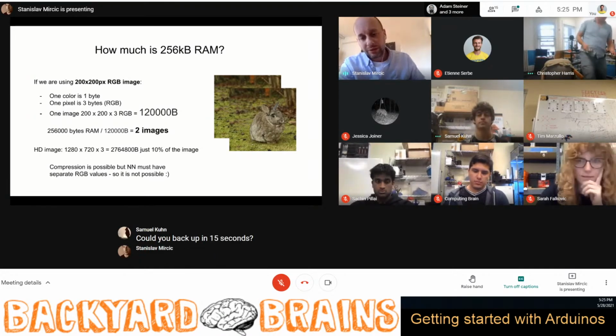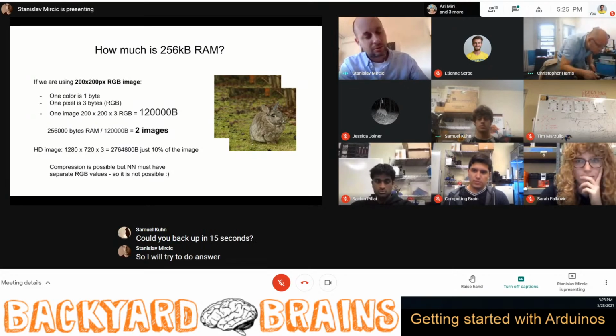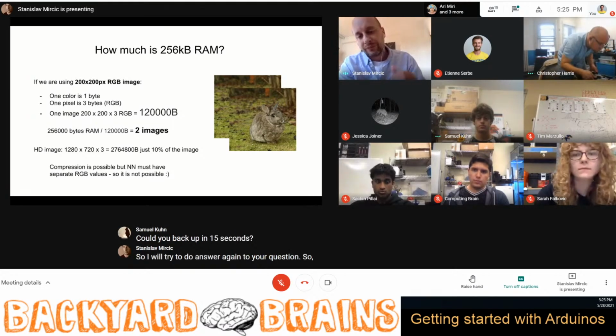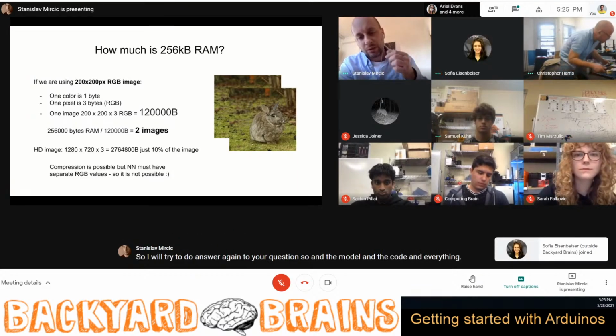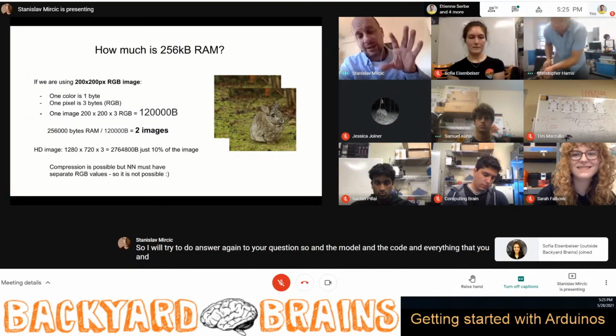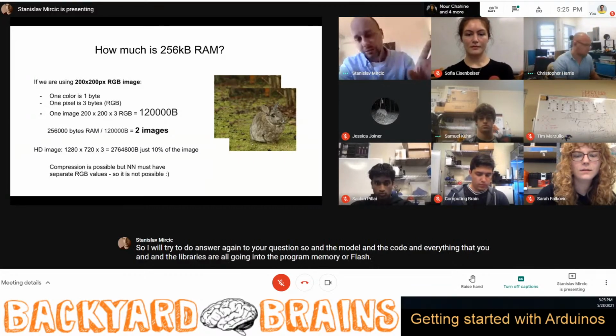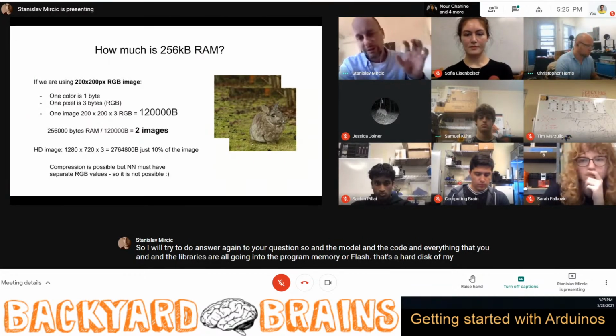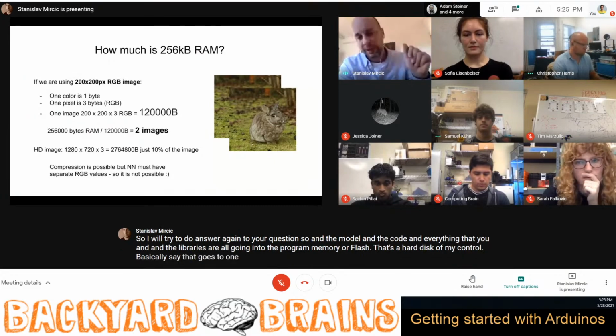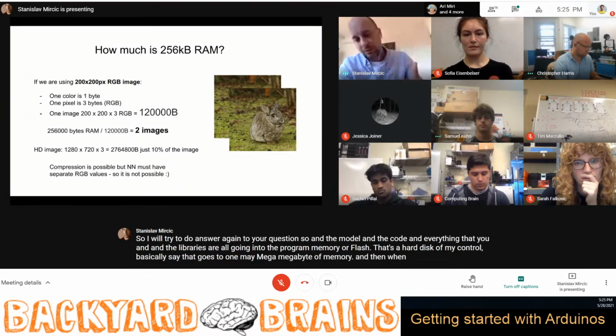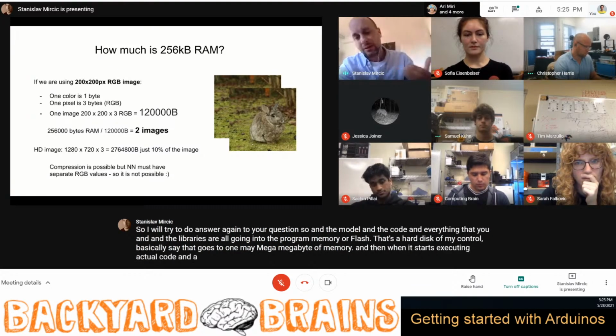Of course. I will try to answer your question again. The model, the code and the libraries all go into the programming memory, or flash. That's the hard disk of the microcontroller basically. So that goes to 1 megabyte of memory, and then when it starts executing the actual code and model, you use RAM memory, and you will not copy the whole code into RAM.